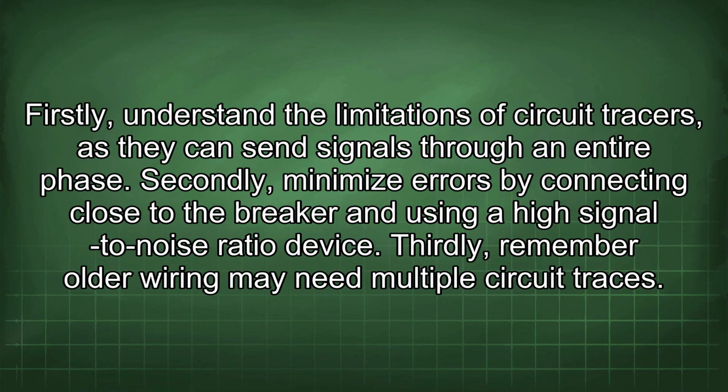Firstly, understand the limitations of circuit tracers, as they can send signals through an entire phase. Secondly, minimize errors by connecting close to the breaker and using a high signal-to-noise ratio device. Thirdly, remember older wiring may need multiple circuit tracers.